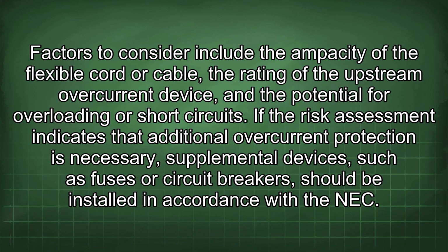Factors to consider include the ampacity of the flexible cord or cable, the rating of the upstream overcurrent device, and the potential for overloading or short circuits. If the risk assessment indicates that additional overcurrent protection is necessary, supplemental devices such as fuses or circuit breakers should be installed in accordance with the NEC.